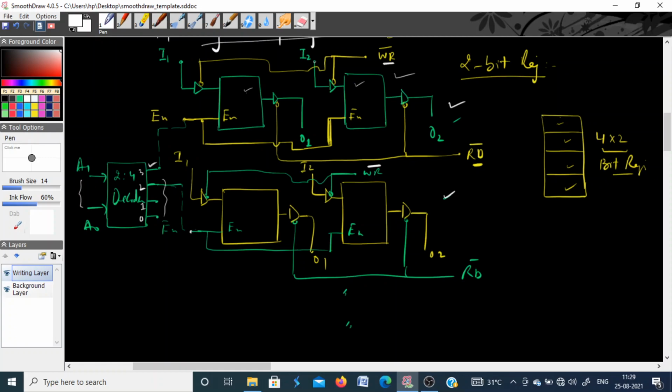Now for read, what we have said is that when you press the read signal, all the buffers in all the flip-flops get activated at the same time because they are all connected together. So this read and this read pin are basically connected together. Okay, all the 4 pins, because at the output of this memory chip we have only one read signal. The single read signal is used to activate all the buffers, whether it is in this register or this register or this register.